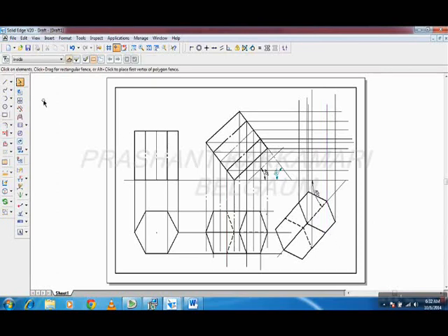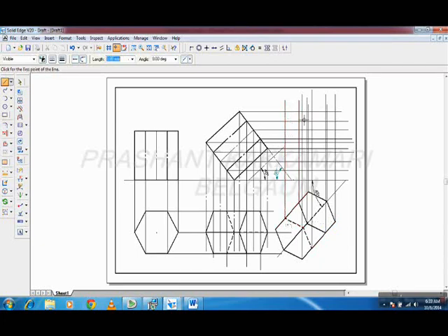So what I will do, once again I will take. So slightly it may be merging with that. Slightly it is merging. If it is not taking like this vertical, or if it is touching here, what you can do is directly enter the angle 90 to reduce the confusion. If you move cursor anywhere, the angle will not change. So this line will be continuously 90 degrees. So anywhere you click it, now come here. So this is also 90 degrees. Okay. From here 90. So all the projection lines, it will take lot of time.